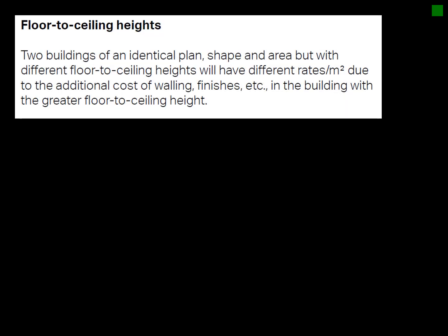Then the other thing, I'm just going to highlight a few things that you can also look at. Your floor to ceiling height also has an influence, or your square meter rate might not always be relevant to a new building, because some buildings may have a double volume type of installation. Your floor to ceiling height might be lower or higher, which will influence the cost, etc. So it's just a discussion on that.